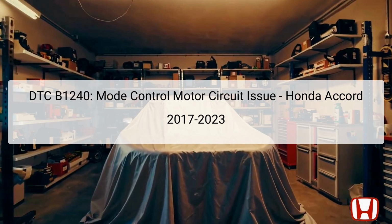The mode control motor plays a crucial role in regulating various air distribution modes in the vehicle, helping ensure passenger comfort. Its location typically involves connection to the climate control unit, situated behind the dashboard. When this DTC is triggered, immediate diagnostics are necessary to identify the root cause, as a failure in this circuitry can lead to improper climate settings and discomfort for the occupants.